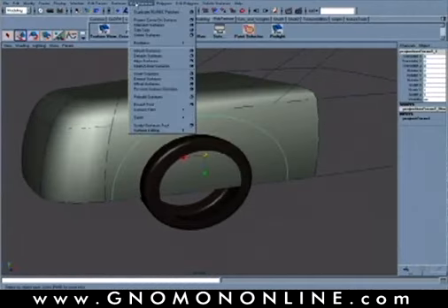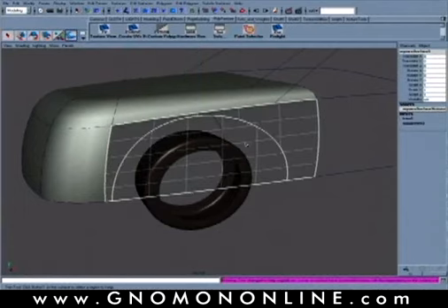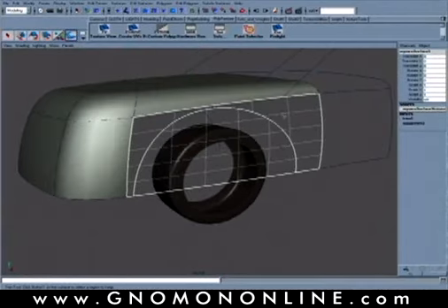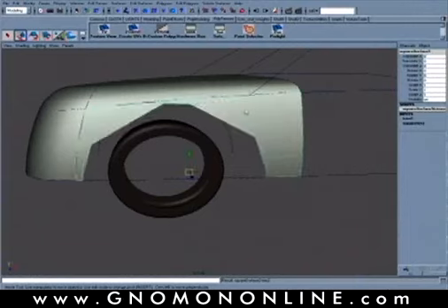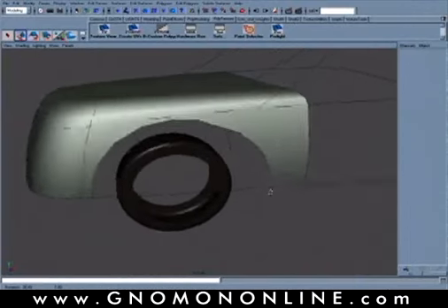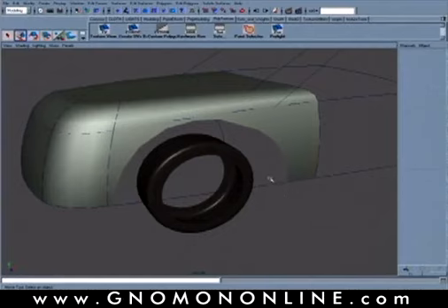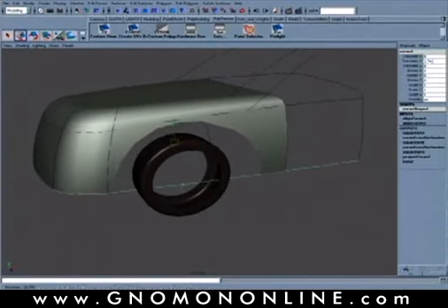So I'm going to go in here under Edit Surface, use the Trim tool, and select my surface that I want to trim, and then I want to keep basically outside of that wheel opening or that larger circle here. So be sure to tag a point out here and enter that, and we basically have then created our larger trim curve boundary.